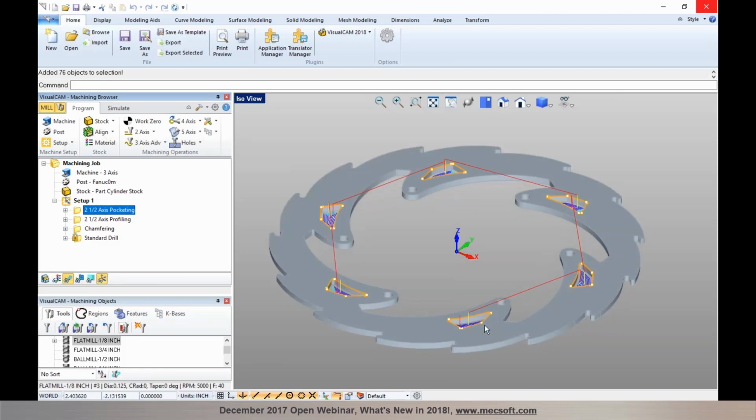To see the toolpath in those hidden areas, you could select toolpath hidden area display, and this is a new option which is available in 2018. As you toggle this, you'll be able to actually look through to the toolpath in the hidden areas as well. You can use a single button click to toggle it on or off. Similar to your toolpath display, you have the option to toggle the display of the hidden areas. This is also a new feature available in both Visual CAD CAM and Rhino CAM 2018.